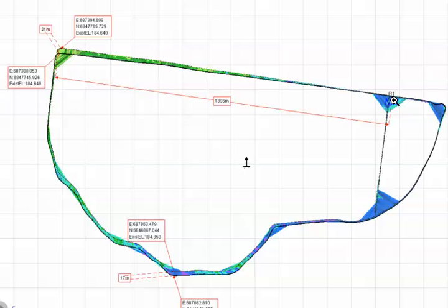And then one other comment is that, yeah, the further we get from the master benchmark, the greater the error. So if you had a small field that was in here or in around the master benchmark, the error is quite small. You can get away with it a lot easier. So these are 100-meter grid cells, so 300 feet grid cells. So yeah, a field that's 400 by 400, it's not too bad at all. You get away with it. But large fields, it is more significant.